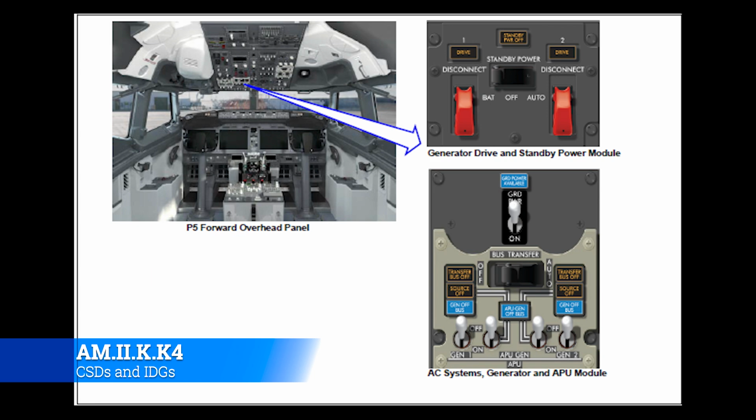The panel right below it, you'll notice the switch where it says ground power on or off, and there's a little blue light above it that says ground power is available. That is the light that I was talking about earlier. If you plug power into the P19 and everything is working well, that light will come on, and then you can turn ground power on by simply flipping it up, and that will basically serve as your infinite battery off to the side. The switches below that, you have a bus transfer relay down below.